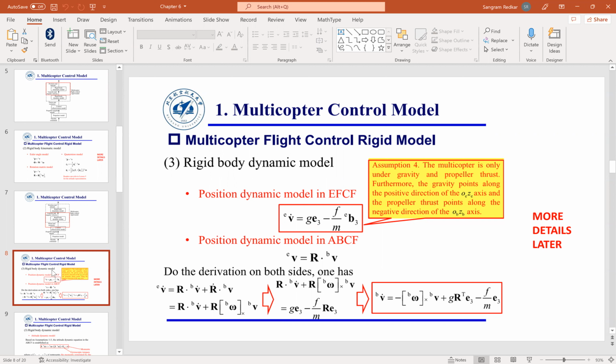So you cannot add dollars to pesos. At the end, all the forces have to be resolved in only one reference frame. It doesn't matter whether you resolve them in the aircraft body reference frame or in the Earth-centered, Earth-fixed coordinate frame, they have to be in the same frame. That's why you are going to have this transformation. That is the reason why you have this rotation matrix.